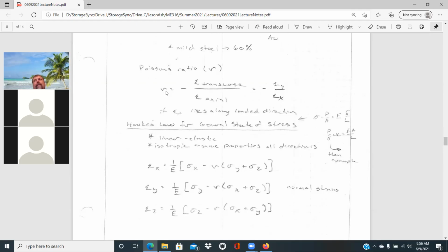As you're dealing with plastic effects, once you get into the plastic region, no matter what your Poisson's ratio was in the linear elastic region, it generally will shift to that higher end, 0.5, after it yields. And for those odd materials that I mentioned, like the spherical ball that expands in all directions as you pull on it, that would have a negative Poisson's ratio. They can do that from a microstructural standpoint, but again, it's not very common from a practical standpoint.